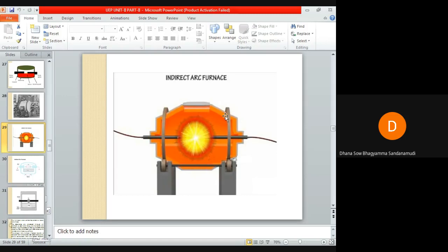The walls are absorbing the heat, since refractory lining is provided to these walls. When the charge comes in contact with the walls, it takes heat from them. So the charge takes heat not only from the radiated heat of the arc, but also from the refractory lining of the walls.